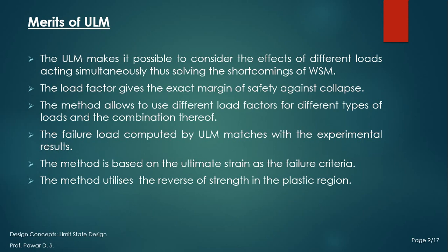So ultimately there are some merits of the ULM also. In the ULM it is possible to consider the effect of different loads acting simultaneously, thus solving the shortcoming of the WSM. Load factor gives the exact margin of safety against collapse. This is the merit of the ULM. The method allows the use of different load factors for different types of loads and their combinations.